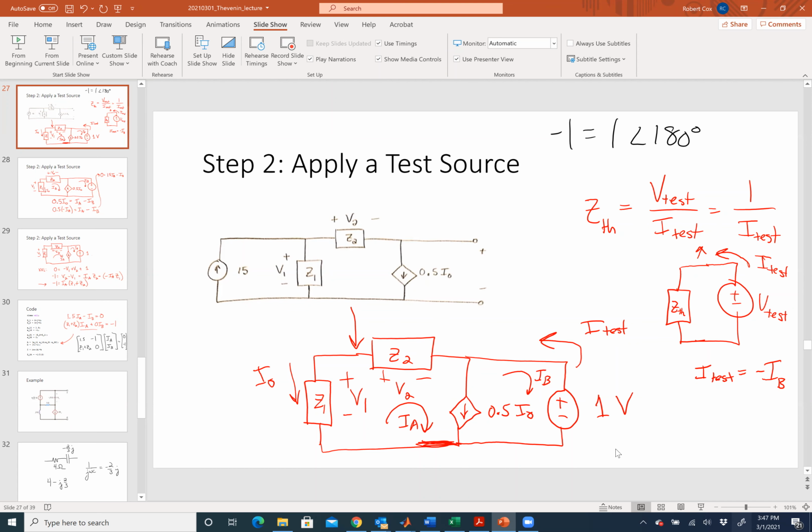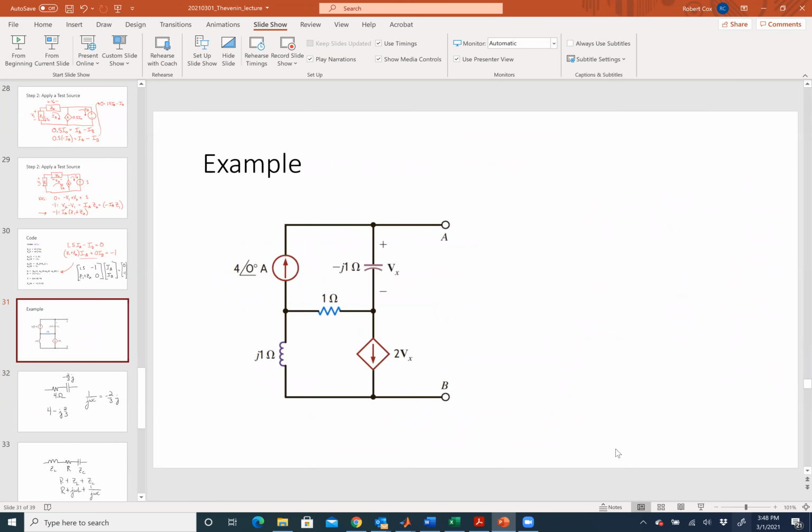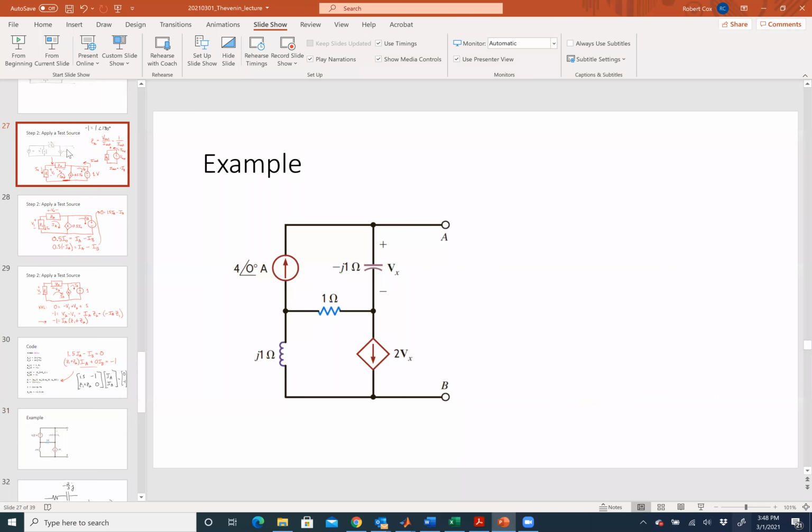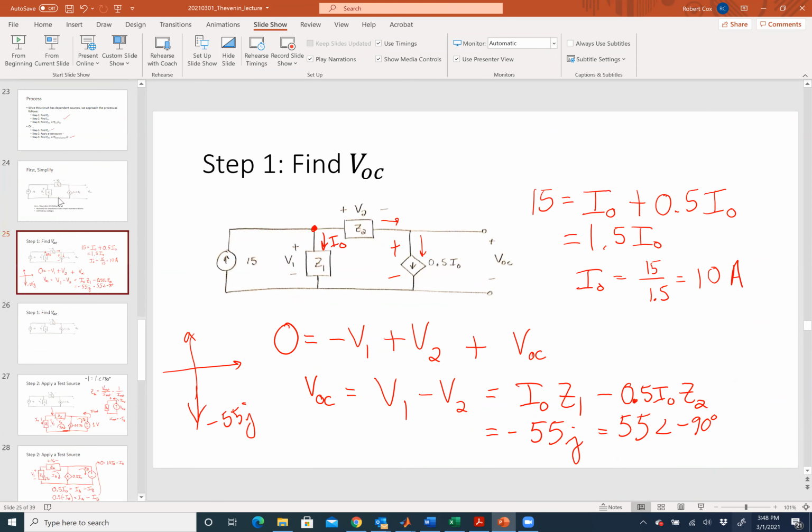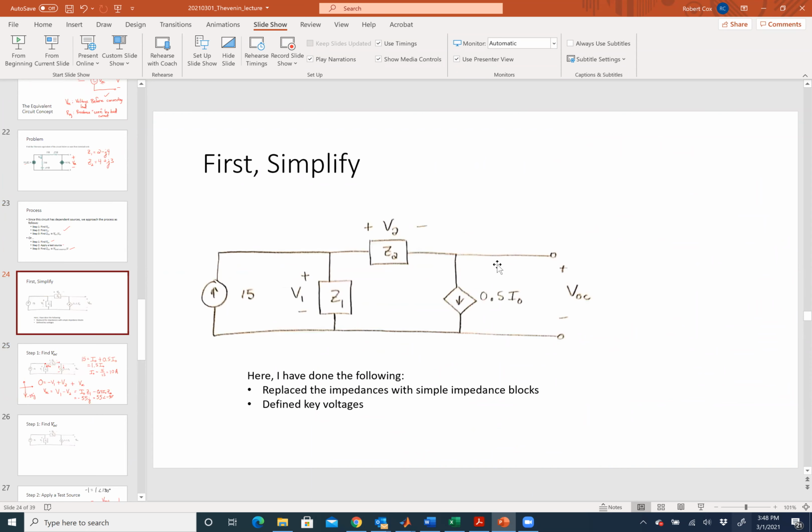All right. Any other questions out there? You said that you could use a current source. Does it matter, or are there situations where a current source would be better than the voltage source when you do a test? So it doesn't matter. In this case, I could use either method, right? So if I had done the problem that we're looking at here, and I was given the original circuit, I put a voltage source in there because I wanted to use mesh. If I put a current source in there, I probably would have used nodal instead.